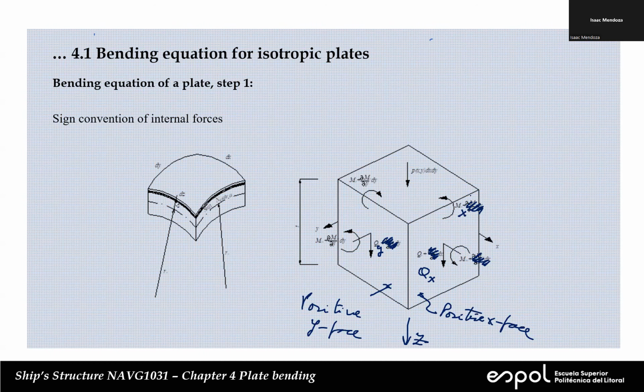People, be careful, because in this case we have bending moment and torsional moment. With your thumb pointing in the y direction, this is the bending moment, Mx. Now, with your thumb pointing in the x direction, that's the torsional moment. This here is Mxy.